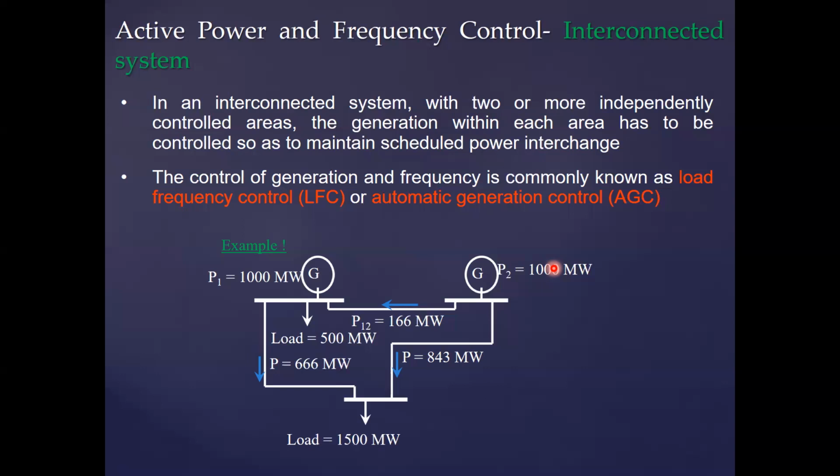Then we take into account the power transmission loss in the network and its cost. We formulate an objective function as a function of the generation cost and the cost of the power transmission loss, and then we try to minimize the overall cost.